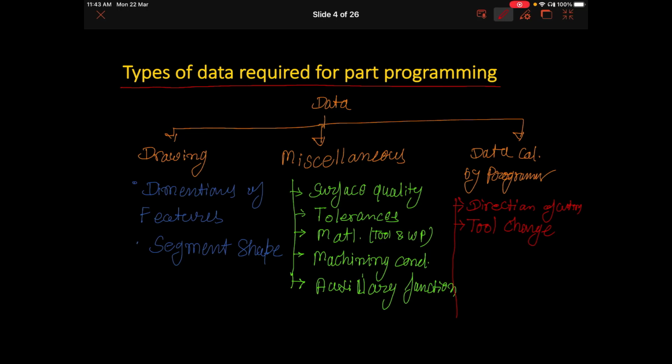The machine requires some time to change the tool, a few seconds, but still we can't change the tool again and again during the operation. So we have to optimize this strategy and optimize the tool changing sequencing, that requires familiarity with the NC process. That is basically related to the NC process, so we can skip that point here.